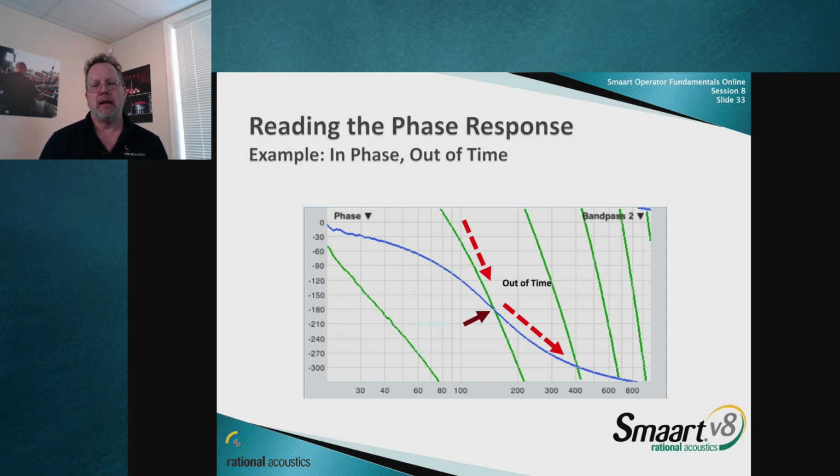And so the old dog way of doing that is to go, okay, first figure out where your crossover is. So, measure your low system, measure your high system, figure out where they're equal level, and then at that point, flop the polarity of the sub and play with the timing until you get the biggest null there, because that's the equal level point, right? So when I get them to be 180 out from each other by adding or subtracting delay, I know they're 180 out. Then I reverse the polarity of the sub again, and I've got addition through crossover.